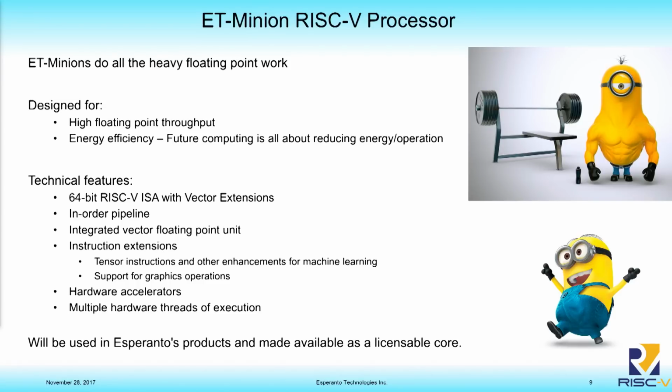Our second core, we call it an ET Minion. And a lot of people have used the name Minion. Again, this was kind of a code name, so I'm calling it ET Minion so you can distinguish it from your own minions out there. But the goal of the Minions is to do all the heavy floating point work. So these are designed to do a lot of flops per clock, but they're also specifically designed in a particular style for energy efficiency. Future computing is all about reducing the energy per operation here.